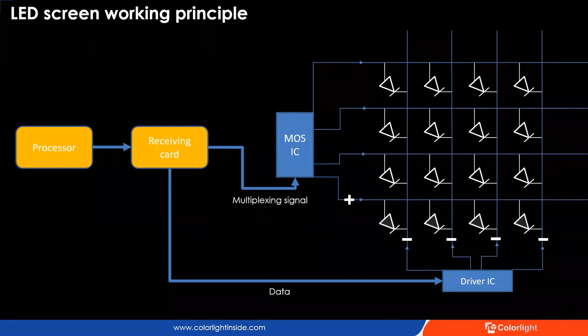Imagine that if this cycle is completed in 4 seconds, so each LED's on time in a row is roughly 1 second, your eye would perceive it as flashing. Now, if this happens fast enough, then your eye doesn't perceive it as flashing, but rather perceives it as on.